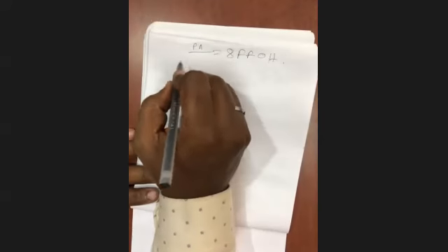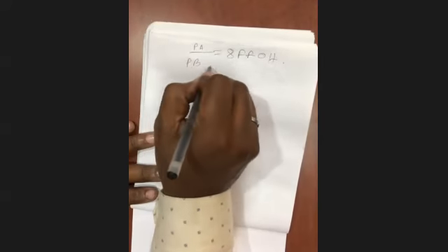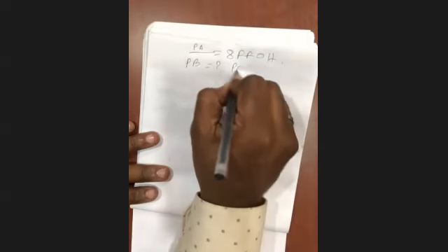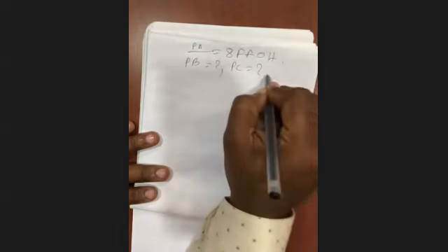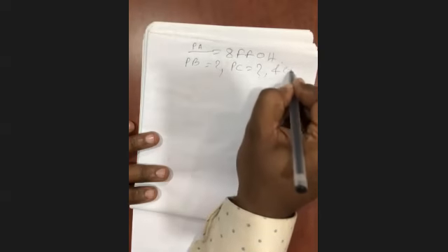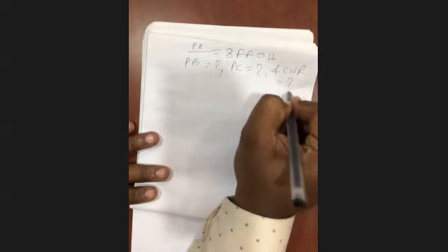if the address of port A is 8FF0H in memory mapped IO, then calculate PB, PC and CWR.